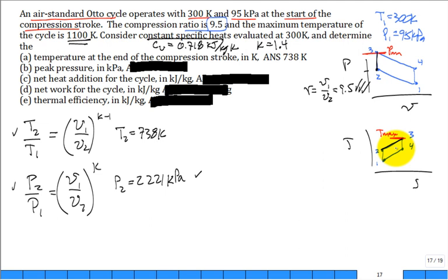But other people that got the right answer, they said, I know there's a whole long list of properties. Just every now and then it's good to make that list of properties. The list of properties typically is pressure, temperature, volume, internal energy, enthalpy, entropy, and flow exergy, but I ran out of room. So you say, what's constant during the process from 2 to 3? Is pressure constant? No. Temperature constant? No. Bingo. Somebody observed the specific volume is constant.